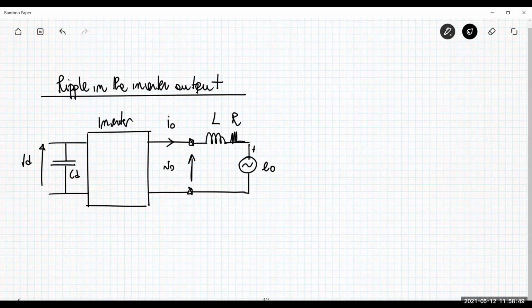Remember the superposition effect that we considered when we talked about the ripple in the DC to DC bidirectional converter. We separate two different circuits: in one you have just the DC quantities, which is related to something constant, not involving the ripple, and another circuit in which we have just the AC contribution, which does not have any average value.